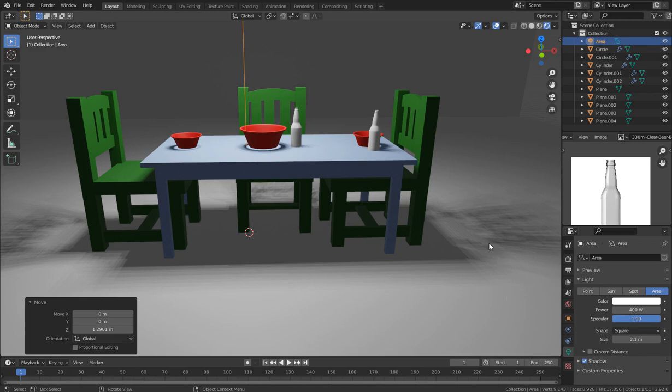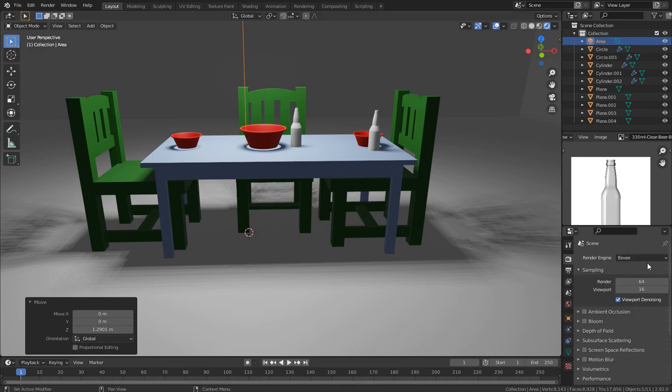But like I said, with the renderer, we can come to the Eevee render settings. Remember, in this part we are dealing with Eevee. The other part we will talk about Cycles and Workbench. So this is the Eevee renderer. When you enable ambient occlusion, you see it will add some lighting from the objects in individual places. Watch this particular place, you see what I'm talking about. That's ambient occlusion. And if we add bloom, it will just increase the environmental lighting. It adds some shady lighting. Watch as I demonstrate. We don't want bloom here.